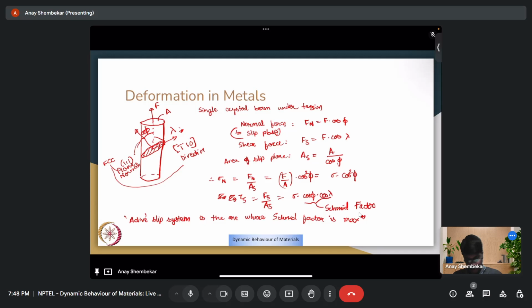There are other mechanisms of plastic deformation. These include martensitic transformation, which is widely seen in shape memory alloys, wherein the material undergoes a transformation between two different underlying configurations in order to minimize its overall energy. That typically leads to some small changes in volume, which may be permanent.